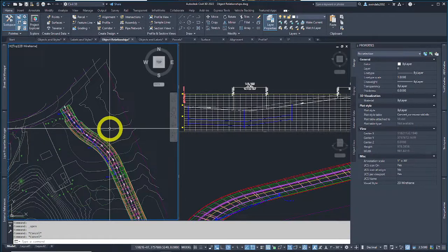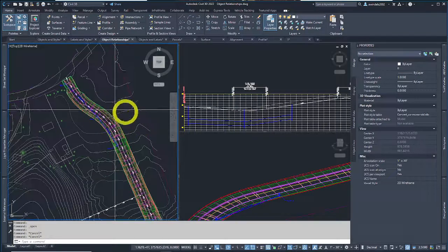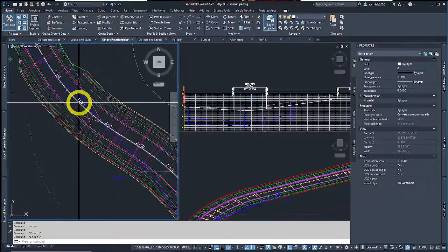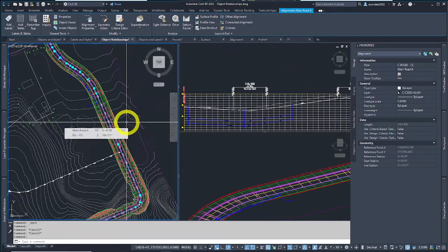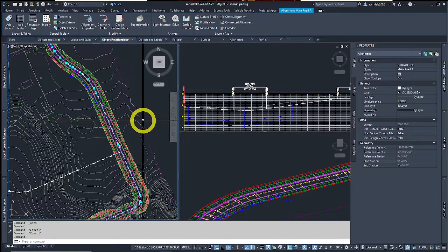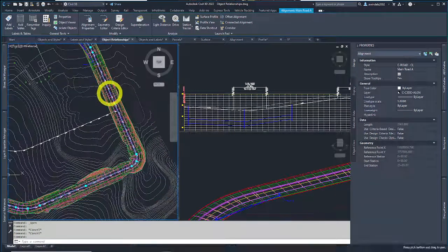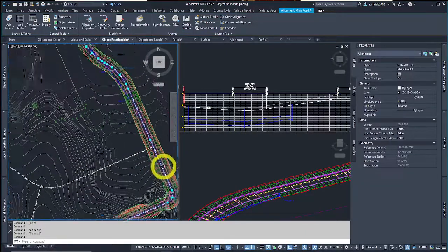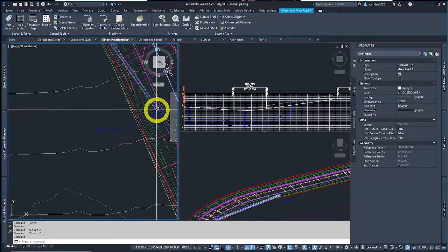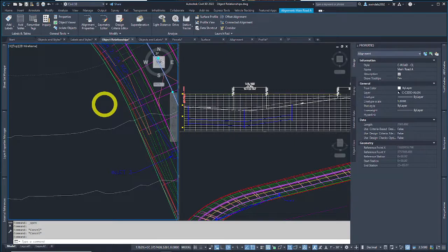So on the typical land development project, there are dozens of designs that work together. For example, now we're in this drawing and we started developing this site. A lot of times we start with this profile. The centerline of the profile is a backbone piece. So it's saying a lot of times, and this is the case in the real world, the road is designed first by drawing this 2D path centerline. A lot of things are built from that. Other roads over here, how it's graded out, sewer systems hitting it, these storm pipes touching it, anywhere the parcels touch the centerline of the road possibly.